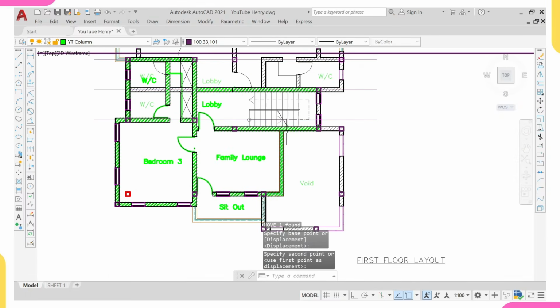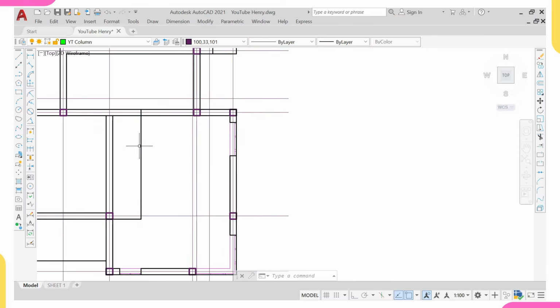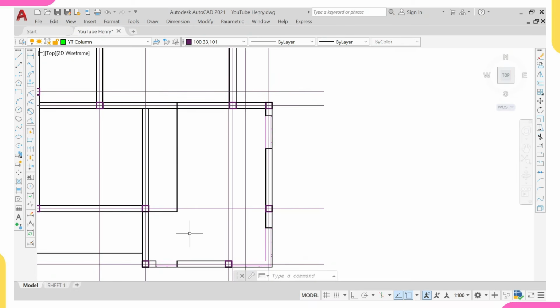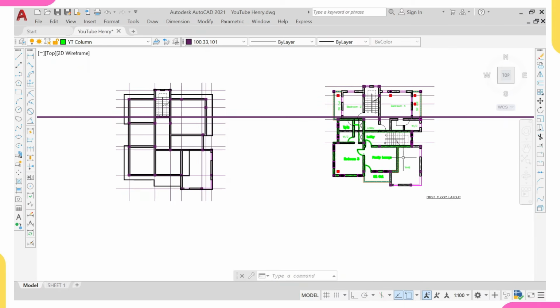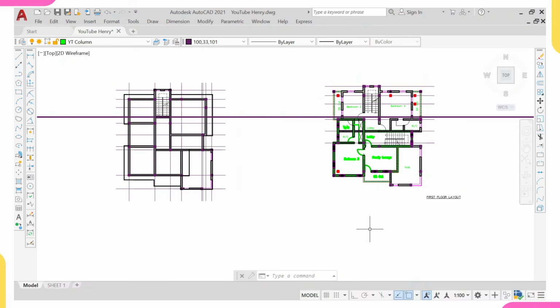So at this point, if you are seeing this, the roof beam is now covering our cantilever. The cantilever that we have here, it is covering it. So that means I have to insert a grid line here and here to be able to model this beam. Remember, I told you before, to be able to model any beam or column, there must be a grid line here before you can model it.